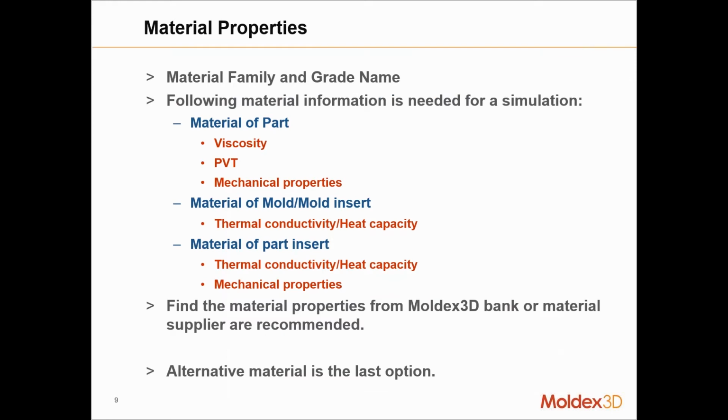When you talk about your material properties, the rheological properties of a material can vary, even though it is the same material supplier, even though it is a similar grade, even if the melt flow index is the same. The viscosity or the PVT behavior could be very different, which means the actual rheological properties of the material need to be captured as much as possible in the simulation. And they include your viscosity data, your PVT.